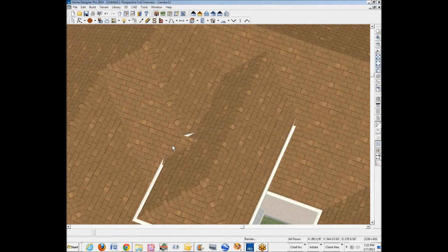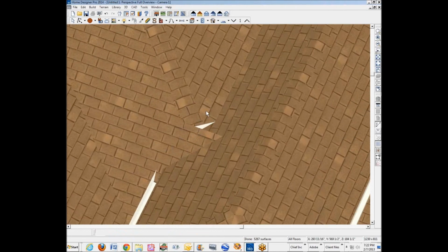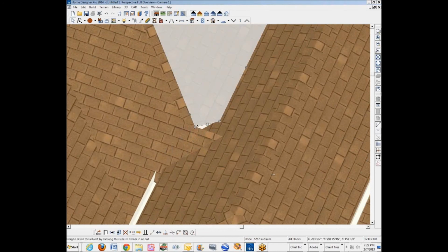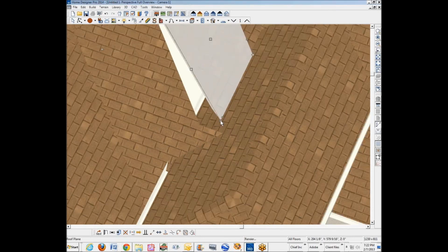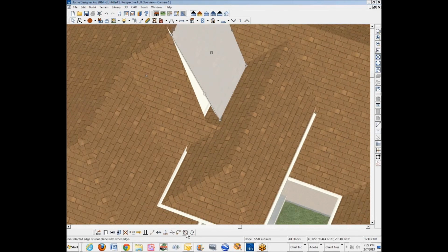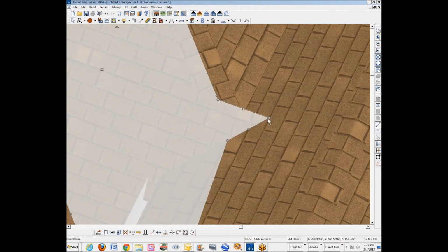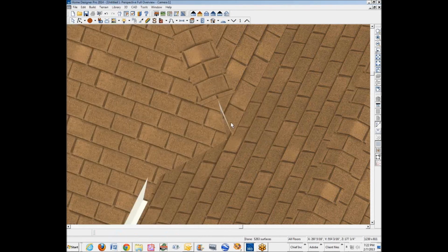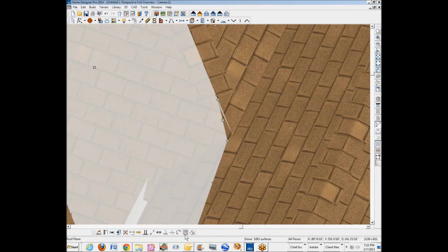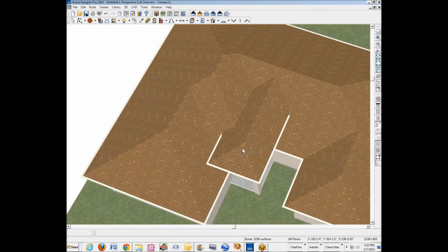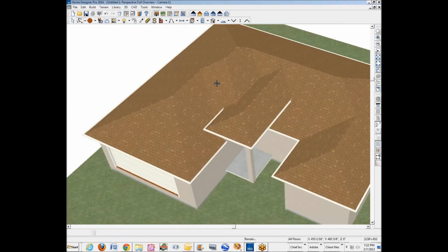That worked. Now, how's this going to work? Probably just goes away. I'm going to get rid of that by dragging that break point into another break point, and then tie that ridge in. Okay, now it's beginning to look a little more finished. This piece here is not going to go over into here like it was automatically built, so I'm going to get rid of that joint there. You notice I'm ignoring those error messages because they're just communications. They're not necessarily anything I need to know. But I've been doing this for almost 20 years, so I can say that airily.